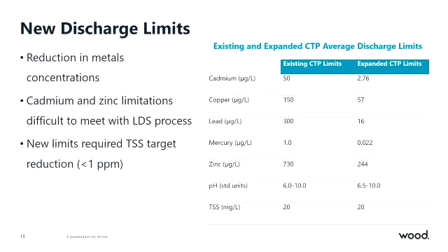Just briefly to look at the change in discharge limits. These are monthly average discharge limits, so not instantaneous maximums, but you can see across the board we saw a reduction in metals. Cadmium and zinc being two of the primary drivers and indicators of both plant performance and also the requirements for the upgraded process. And then I should note that TSS didn't really change with the new limits, but we had to target a TSS of around 1 ppm, and that's because of correlations between TSS and zinc. If we started to have higher concentrations, we could potentially have zinc exceedances.